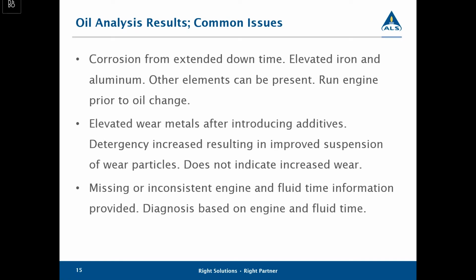Missing or inconsistent engine and fluid time is a tough one for us, and this kind of goes back into the extended downtime. When we don't know what the time is between the last sample and the newest sample we received, how much time is on that engine or how much time is on that fluid, it's very, very hard for us to diagnose those levels. If that engine had 10 hours on it with maybe the levels that we normally see when there's 30 to 50 hours, there's a problem. But if we don't know that there's only 10 hours on that engine, it's very hard for us to not consider that maybe that's a 30 to 50 hour oil change that is maybe more common for that engine, and consider those normal levels. So it's very, very important that we receive from the customer accurate engine and fluid time.